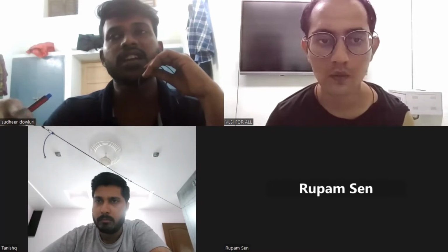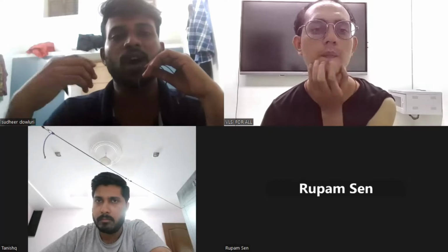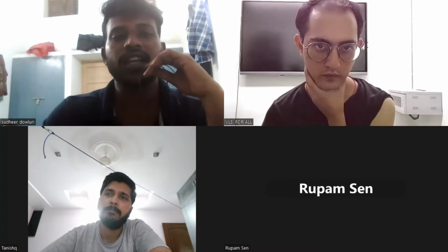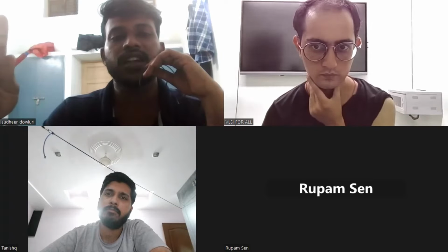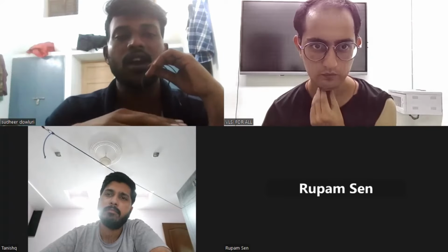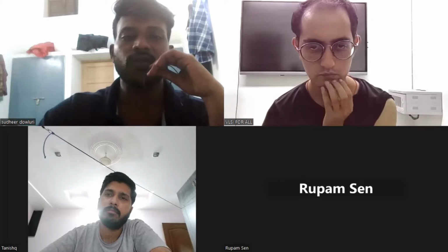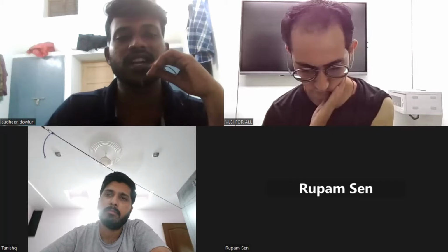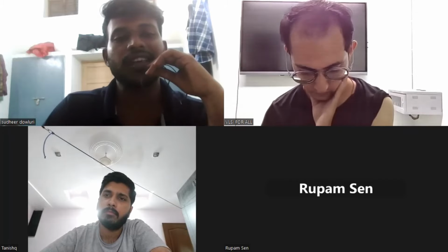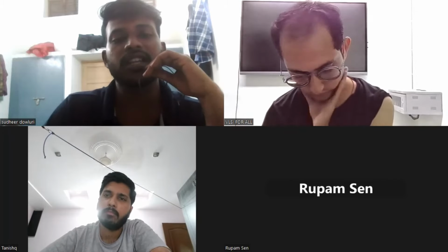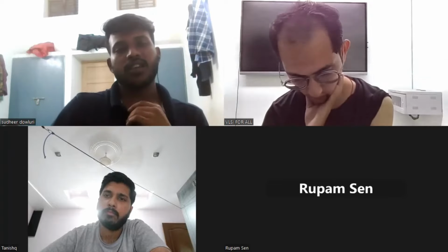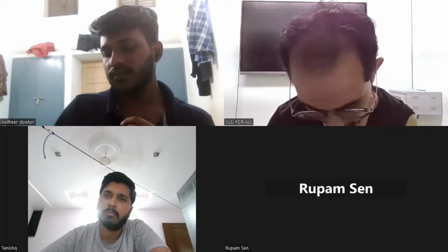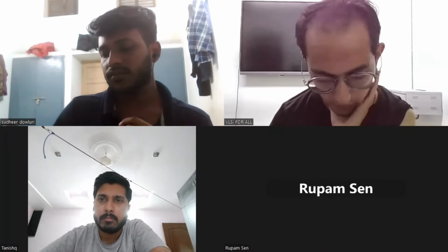A glitch means the output we expect does not occur. For example, static one means the output stays one only. If it goes to zero in between the ones, then it is called a glitch. The expected output is not coming at that time. Can I draw that static zero and static one? Yeah, you can. So Tanish will tell me what the difference is between latches and flip-flops.